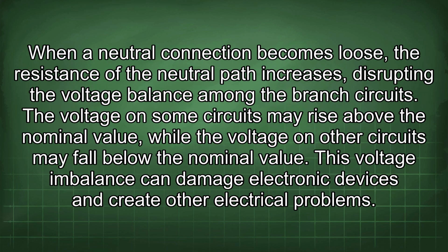When a neutral connection becomes loose, the resistance of the neutral path increases, disrupting the voltage balance among the branch circuits. The voltage on some circuits may rise above the nominal value, while the voltage on other circuits may fall below the nominal value. This voltage imbalance can damage electronic devices and create other electrical problems.